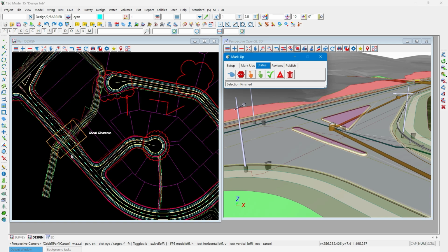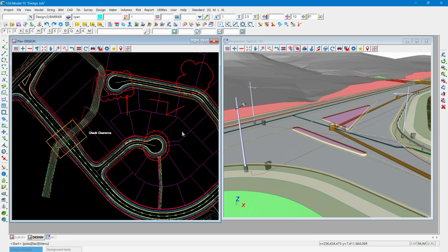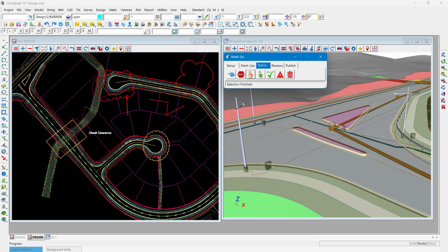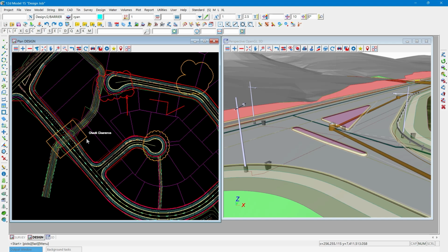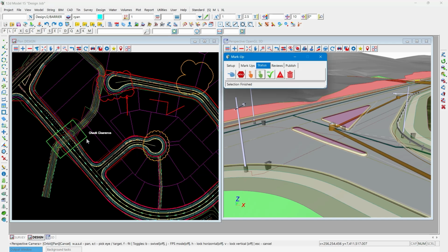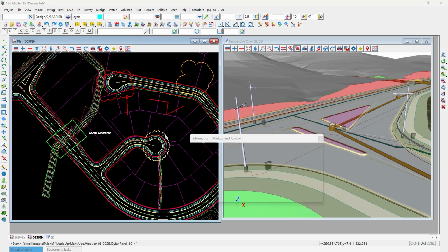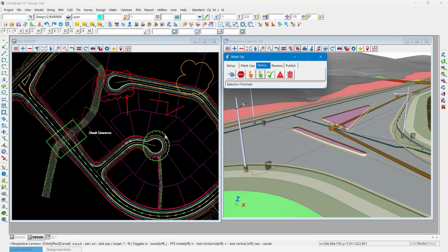So to take you through all of the 4 gateways, I need at least 3 of those in progress, so you would be doing this not so quickly as me. So I've assigned the status gateway for 3 of those markups as in progress. I'll mark one as completed as well, which will change it to a green color. And if I mark this one as complete, a green color. So this would happen over time, obviously, rather than straight away.